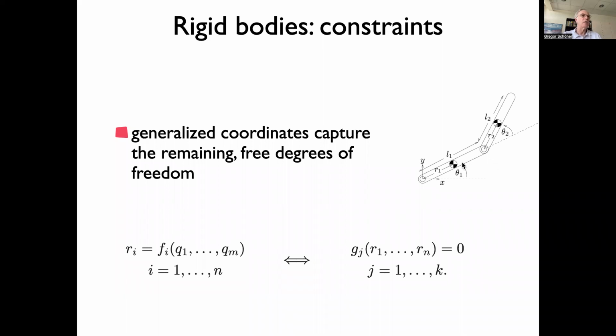And so you can see here, it's very easy. You could just take these joint angles, right? This angle against some arbitrary axis, and then this angle against the previous segment. These two angles very conveniently describe the configuration. And then I would write down an equation that already from the very beginning only has as many variables as there are actual degrees of freedom. And therefore I get rid of all these other constraint equations.